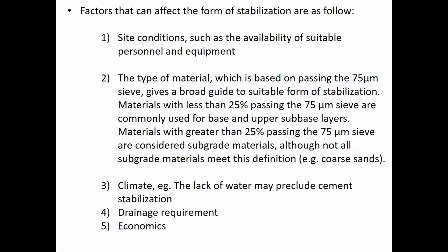For example, if you stabilize the base course, and you have a wearing course of asphalt which is porous, the water can run along the surface of the base course which has been stabilized, because it's sort of waterproof.